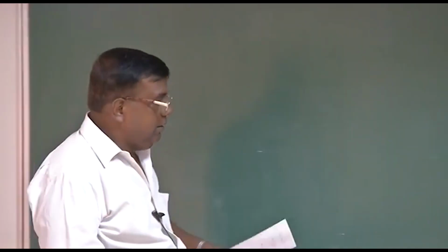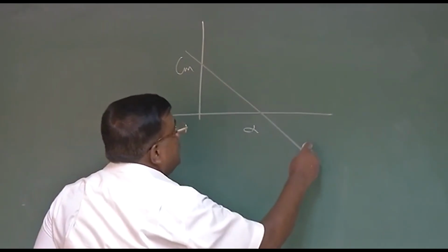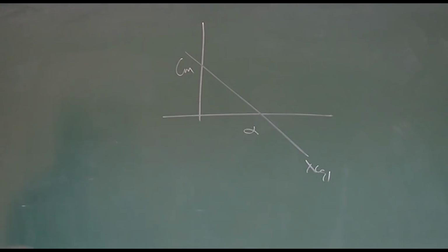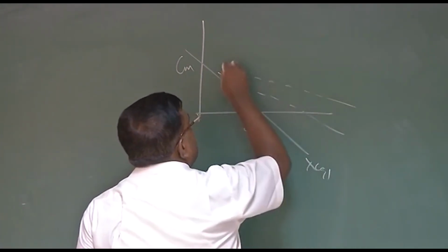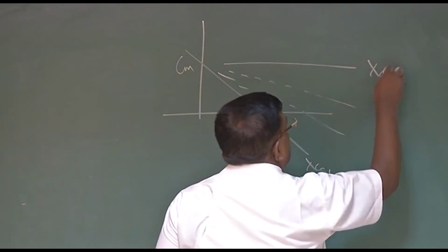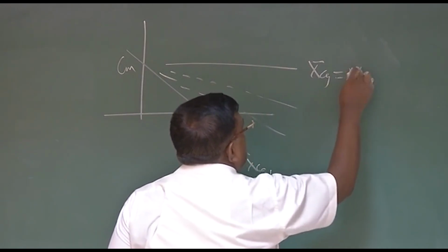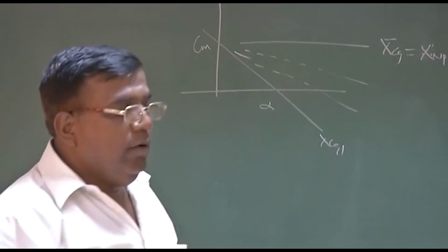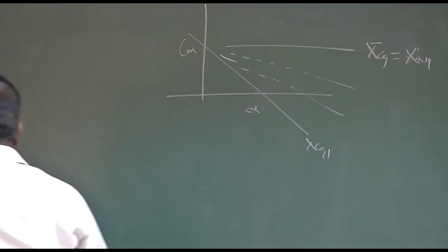Just to complete this part, we have seen one thing. If it is Cm versus alpha, and this slope is for a particular CG, if I take CG aft, right? Okay, then I know this slope goes on changing, and there is a CG location at which the slope is 0, and we call it the aircraft at this CG location has become neutrally stable, and that CG location where the aircraft becomes neutrally stable we call neutral point. So we will try to formulate neutral point also.